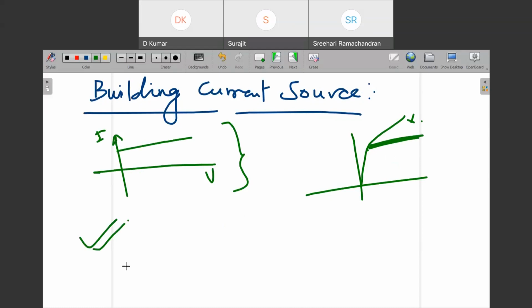Why do we need current sources? What is the need of that? Because we want to realize one important application of the op-amp, that is the integrator. Now we will bring capacitance along with the resistances, and the location of the capacitance matters. If we put the capacitance in front of the op-amp, it will behave like a differentiator. If we interchange the feedback resistance and the capacitance, and place the capacitance across the op-amp, that will behave like an integrator, right?